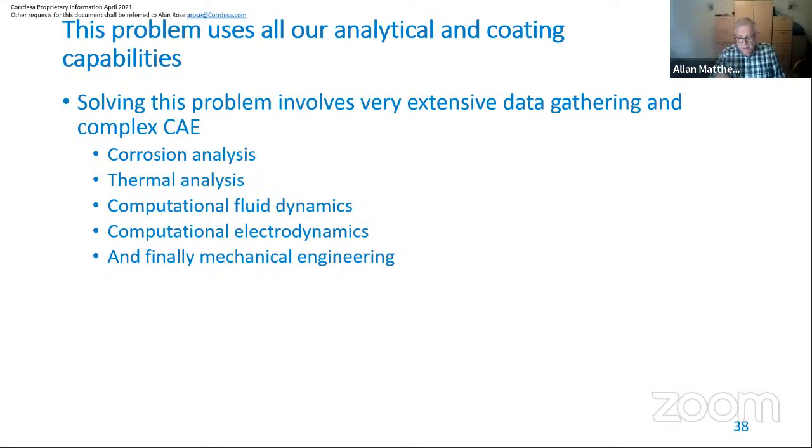There was one other question that you set yourselves. What problems do you have when zinc nickel is nickel rich? Oh, I think we already covered that a bit. As it becomes nickel rich, it goes above the open circuit potential of the underlying steel it's supposed to protect, and now it starts destroying the steel instead of protecting it. So yes, you don't want it going nickel rich.